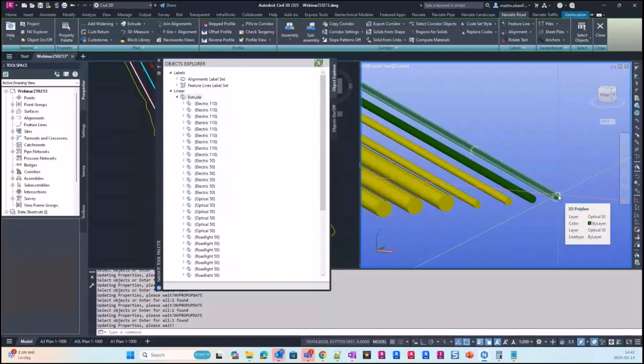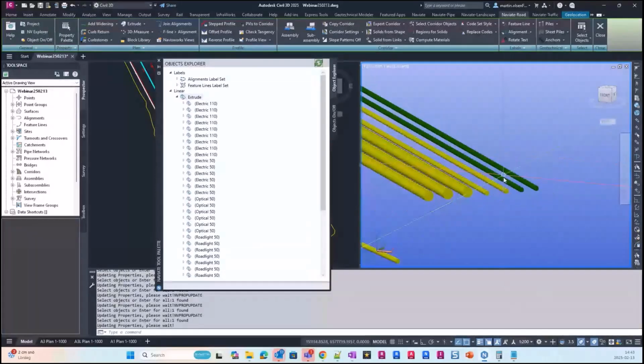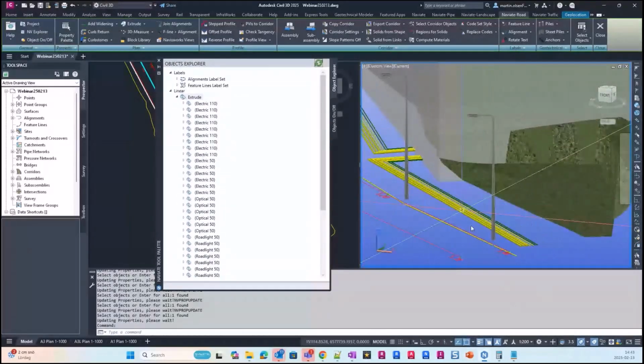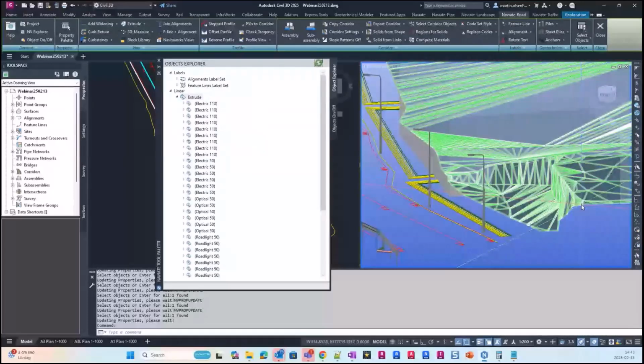So this is basically just a way of scripting the Naviate Extrude command. And now you got the pipes lowered there, or the pipe solids. Yeah, and it's really nice. So if you have a drawing in 2D and you have a finished ground or something, you can just project your lines to that surface, and then you can use this command to script everything to solids.